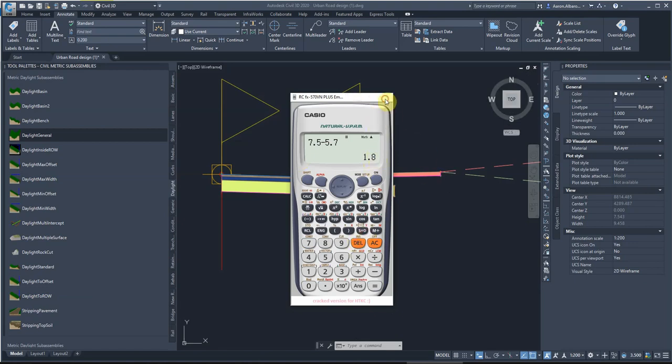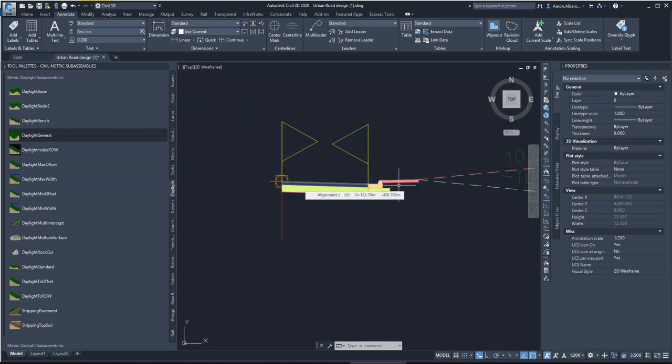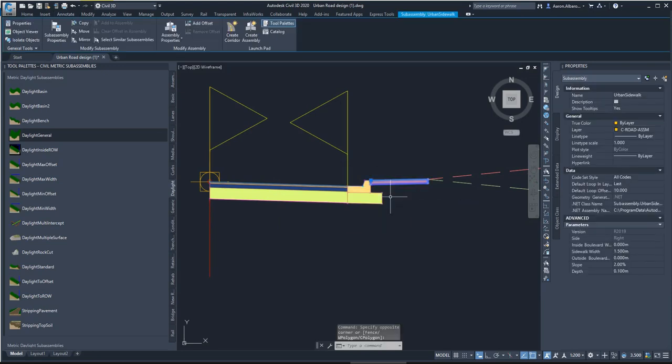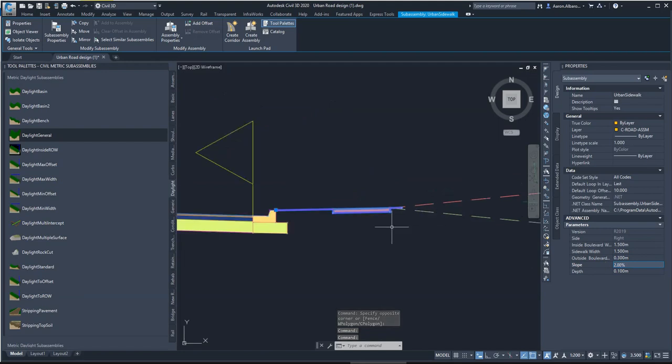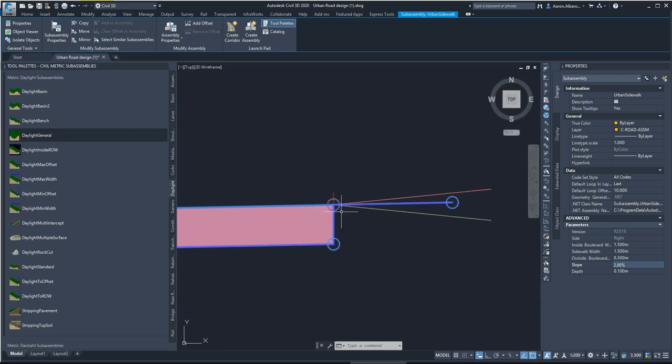So if I create this as my cross section, my road will be narrower than the space I have. So that 1.8 meters I'll add on the inside boulevard. I'll add, because we do need an inside boulevard, 1.5 meters there. And on the outside boulevard, I'll add 0.3. That should fix the difference. And that's what I was saying, because I added the daylight to connect to that link here, by adding the 0.3 on the outside, the daylight didn't move with it.